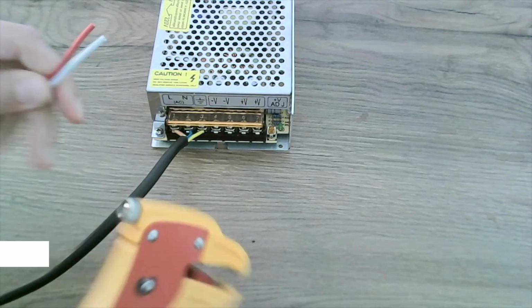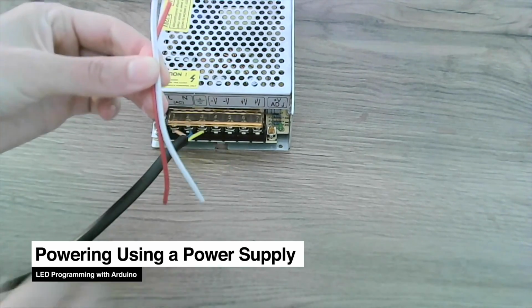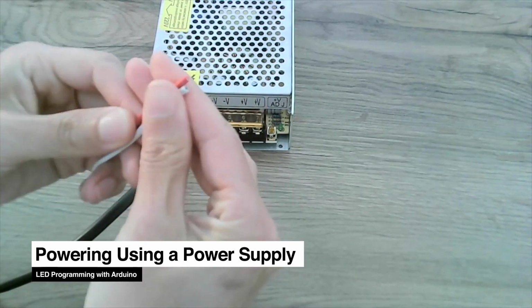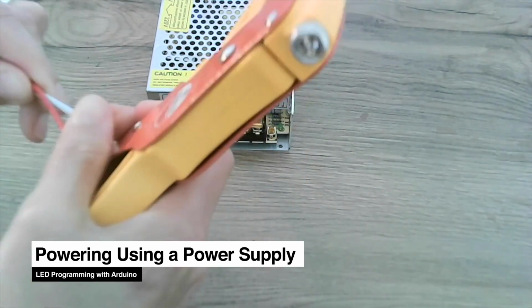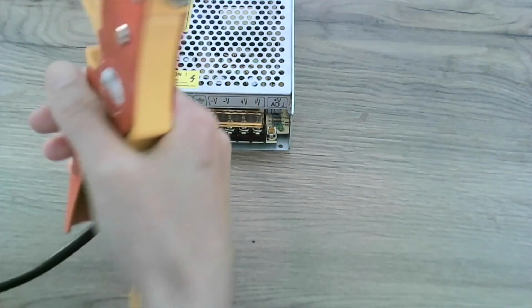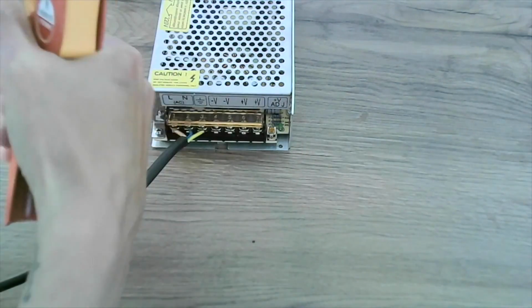In the following section, we'd like to make sure that you have everything unplugged and unpowered. It's very important that you do not have power to either your microcontroller or your power supply when completing the upcoming steps. In order to attach our LEDs to our power supply, we're going to need to attach power and ground. So we'll need 1 wire for power, which is red, and 1 wire for ground, which is either white or black. Strip the ends of your wire to about 1/2 inch or so.